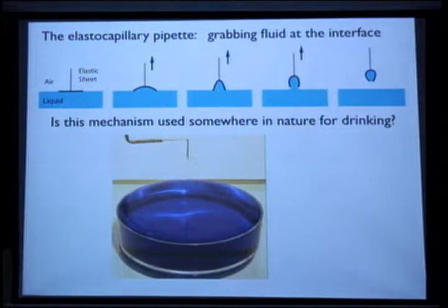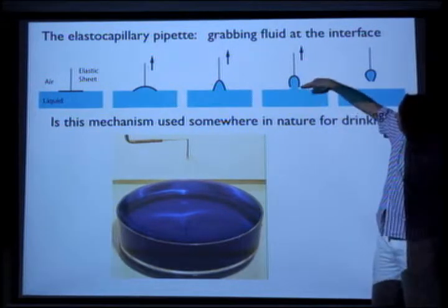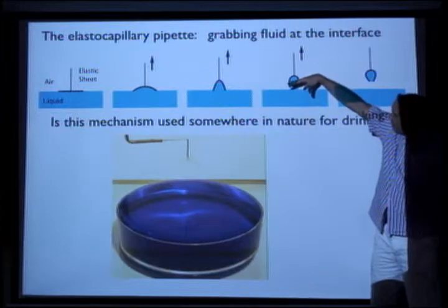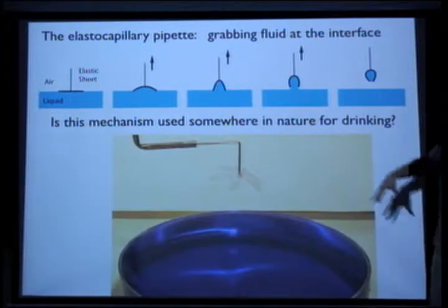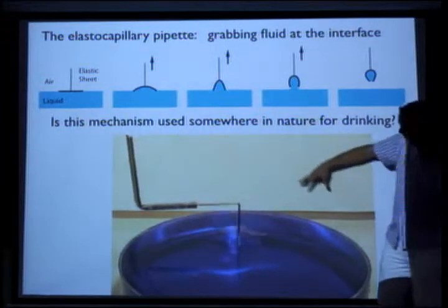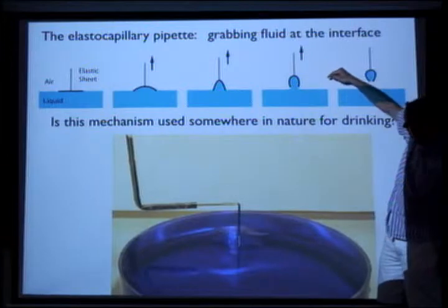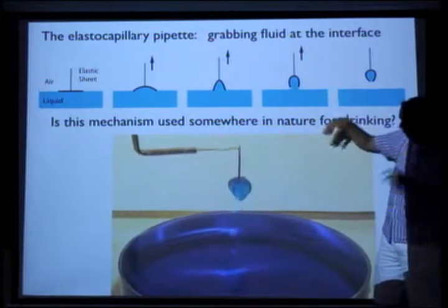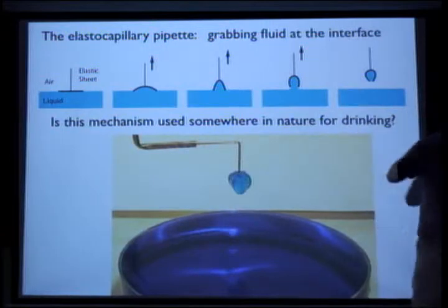So it's basically solids being deformed by interfacial forces. And we turn this upside down. As we lift up, we get a rho g z suction, which causes the thing to close. And provided the petals are close enough together, if they're well cut, then surface tension will keep air from intruding into the suction region, right? So the thing basically zips shut, and you can grab water.